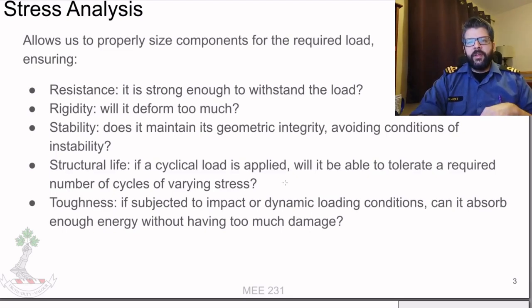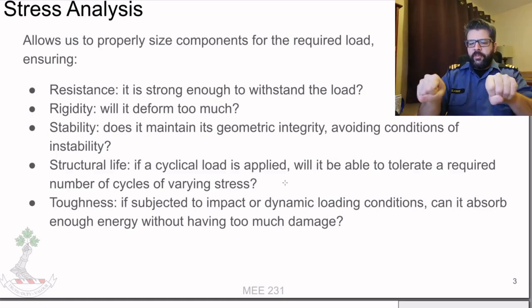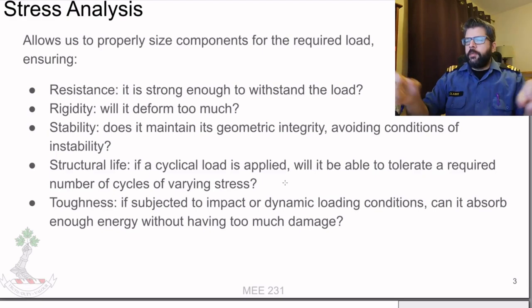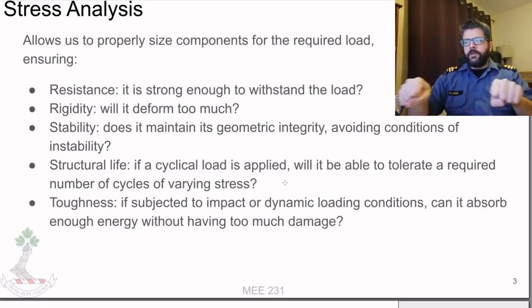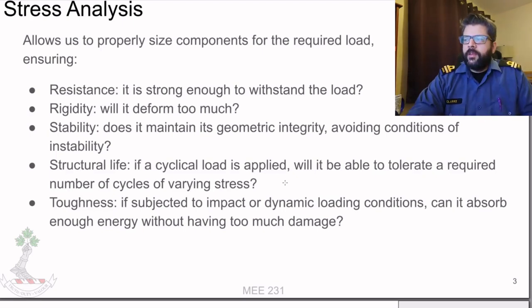So basically, it's a concept we call fatigue. If you apply a load to something and just increase that load until the breaking point, it's going to break. But if you apply smaller cyclical loads to it, so if you're pulling, pushing, then components have a tendency to break at far lower stress levels than they would if it was just a static load.